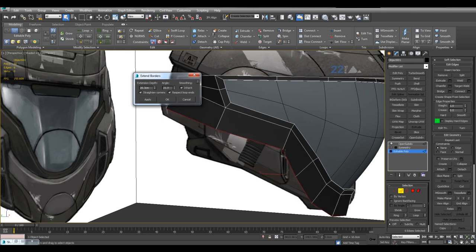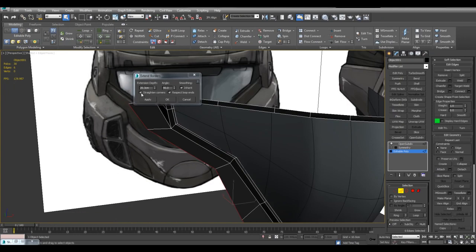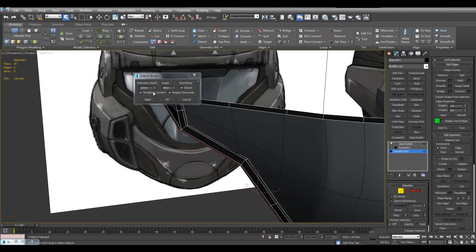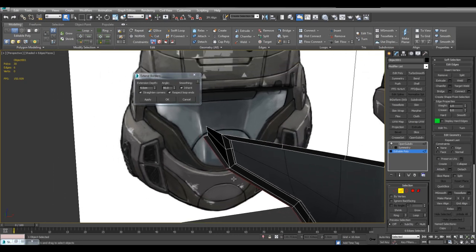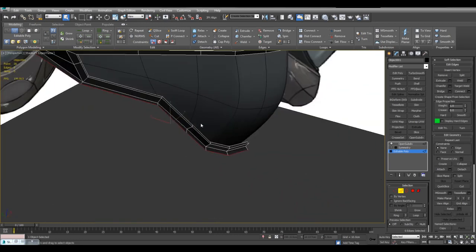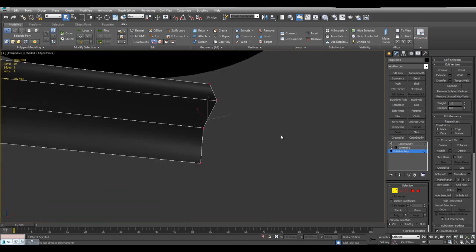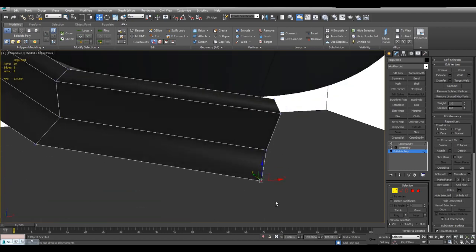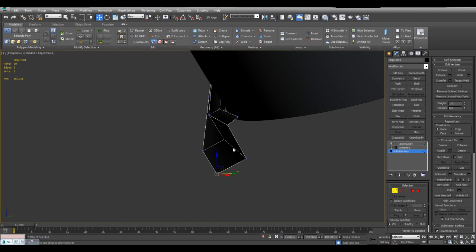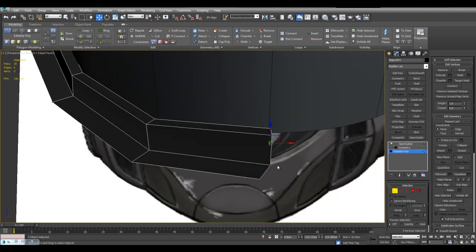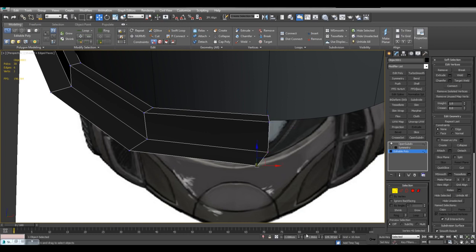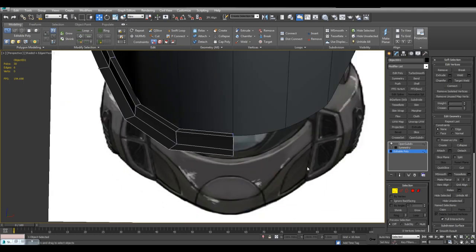And I will set the appropriate angle, which in this case will be 90, and greatly decrease the extension depth, maybe 4. We just need a little bit here. Okay. Now remember, I need to go back here and make sure this is 0. Because I used the script, it went out in this direction, but it's not in the center. These 3 vertices are in the center, but this one also needs to be, so simply right click right here, and this will make the value 0.